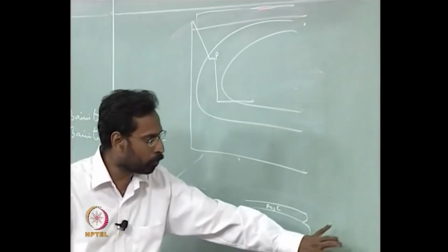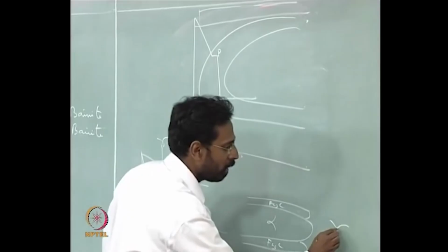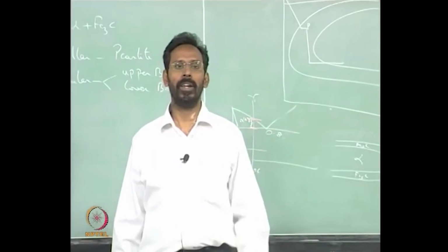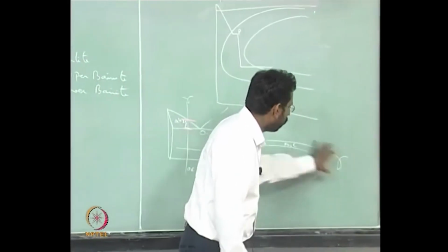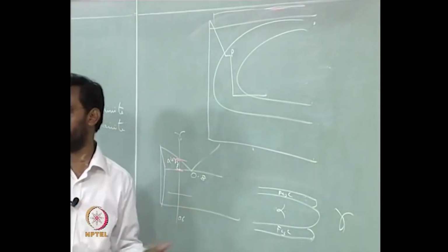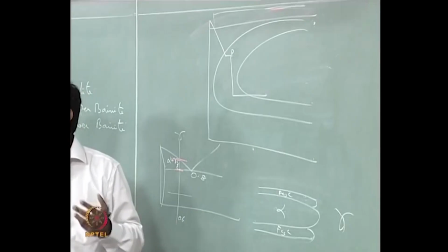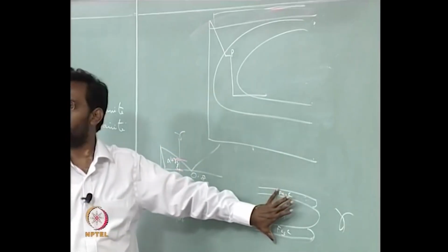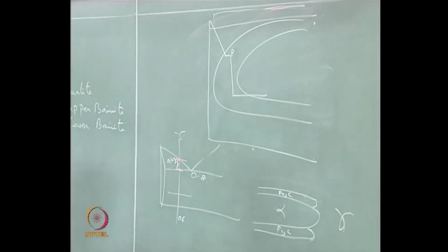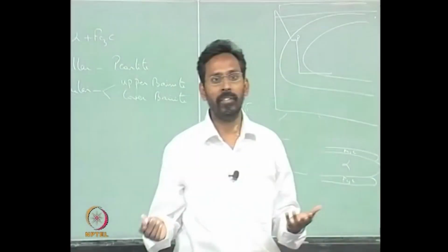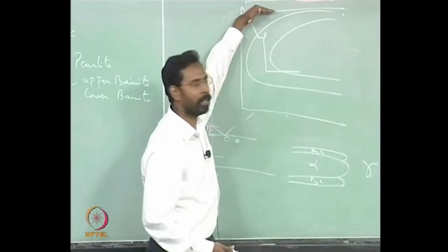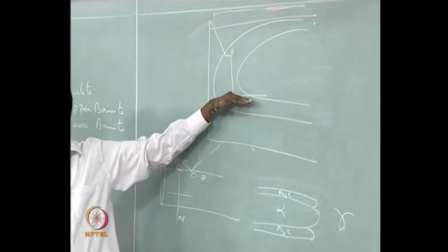So you need carbon atoms to diffuse from the gamma which is here into this. At this temperature that diffusion can be very difficult, because you need a longer diffusion, because from the whole of the gamma grain the atoms have to start moving, and because it is difficult at lower temperature, this pearlite whatever has formed will not grow much. It may grow, but at a very slow rate, but at the same time the gamma that is there is not stable at that temperature, because you are far away from the A1 temperature. So, this gamma has to somehow transform.